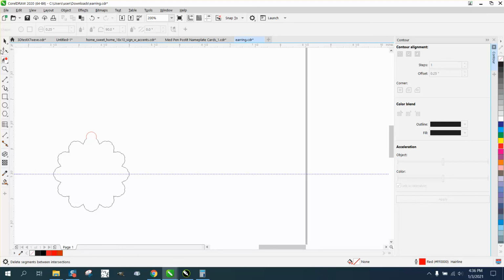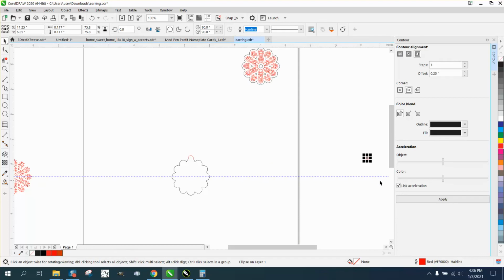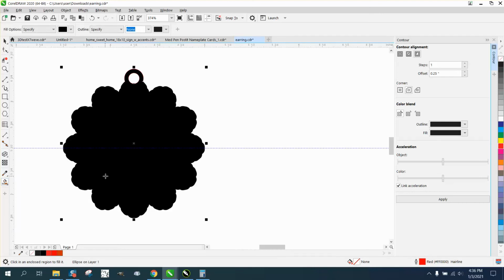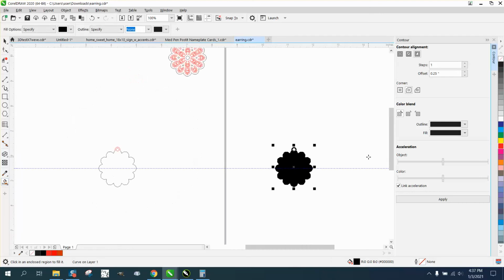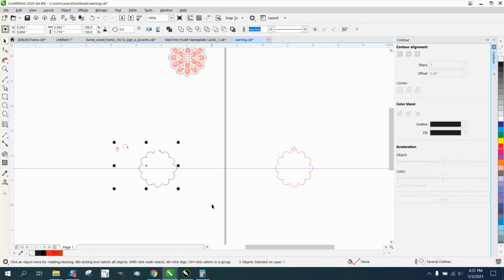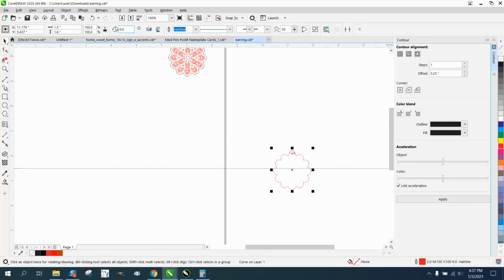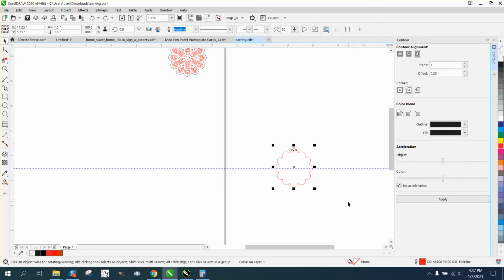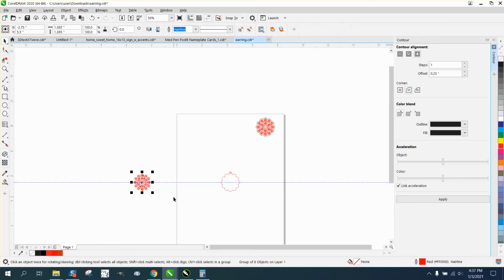Now I would definitely, can't even find my hole. There it is, way over there. 6 inches, long way. That looks pretty good. It looks pretty stout. Use the Smart Fill tool. That is going to fill it in and make it perfect. Make it where all this is solid. And if you don't know what I mean by this, is we have 3 different parts here. Where here we just have 1 part. Now I accidentally moved it, so move it back. And then you can nudge this back to the 3 inches and nudge your part back 3 inches.